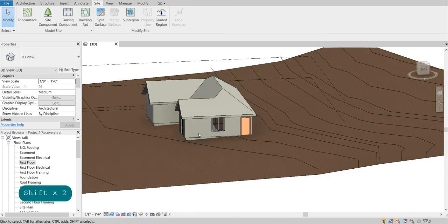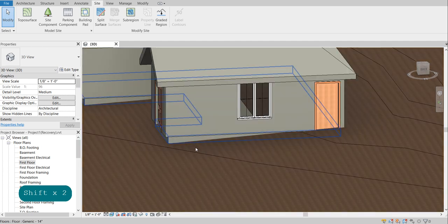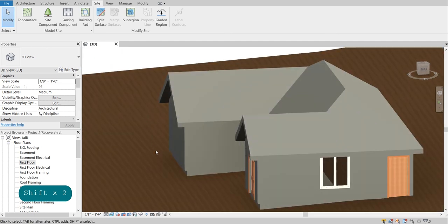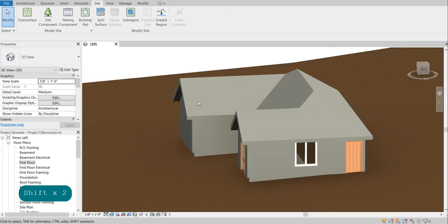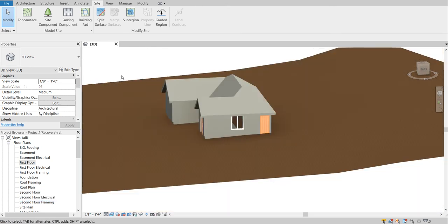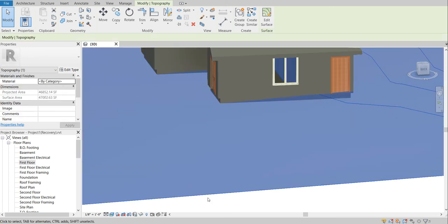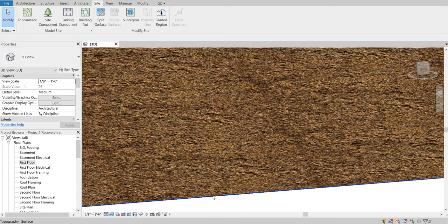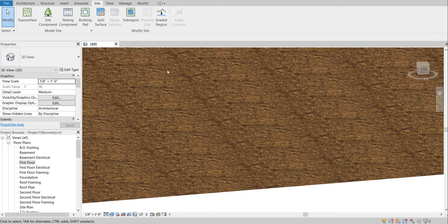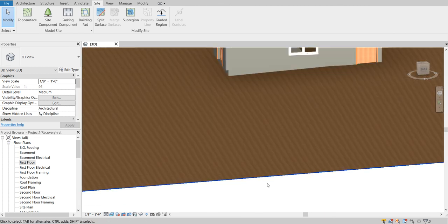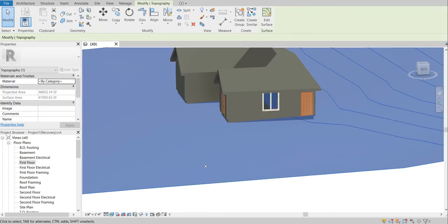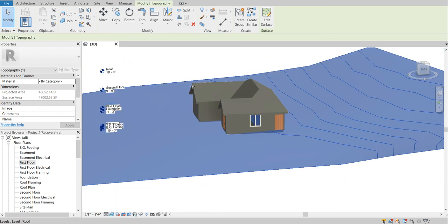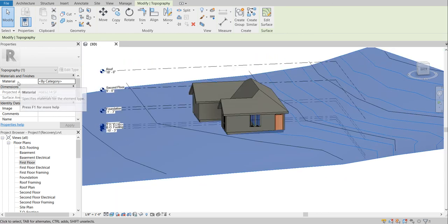Since we haven't really selected any type of materials, we have this grayish surface here, but you can see there's some shades and you see some light, and the contour comes as this brown, like dirt or earth. So this is the material. But I can change this for grass if I want to, like here, by selecting the contour and then coming here to our properties menu.